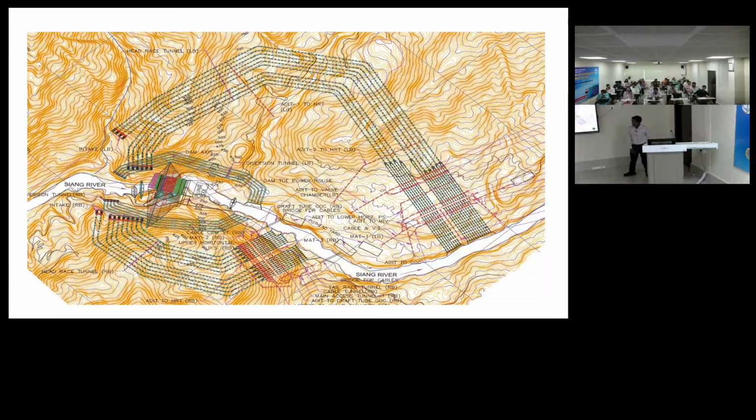Because during the construction, we generally, like I told, what are these? The small coffer dams. Coffer dam means they are temporary, like you want to have a dam here. We just have small dams here first, and here downstream, so that we will completely isolate this area to have this clear working area. So these are called coffer dams. So now divert this water through these tunnels or channels, anything.